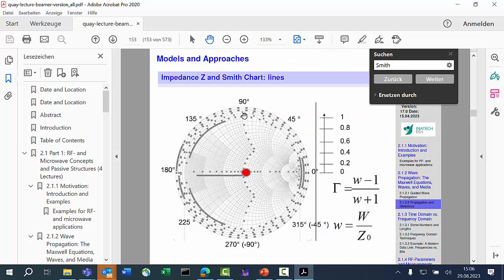So there's a magnitude in this direction, and there's a phase. The only thing is just to visualize: you have some cable with some impedance, and you tell what is happening if you don't connect it, if you connect it with a short, or if you put any other impedances around. For example, if I have a central impedance and I'm connecting it to something which maybe has now a real impedance, then I know I get some reflection.